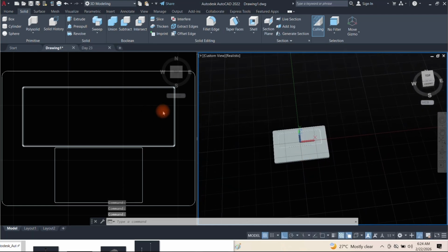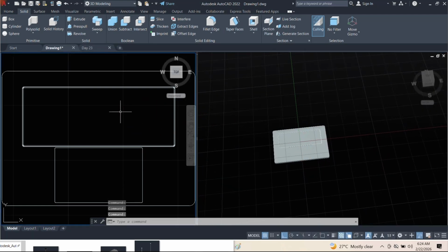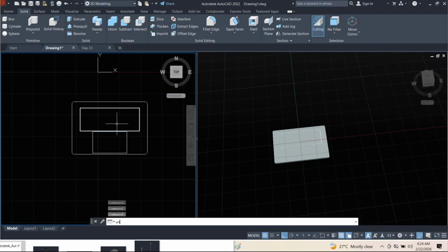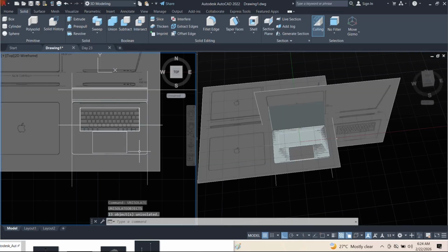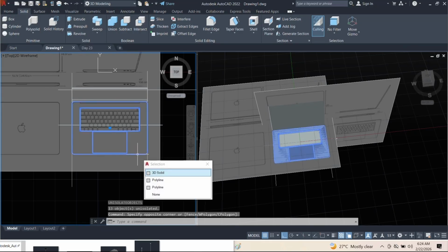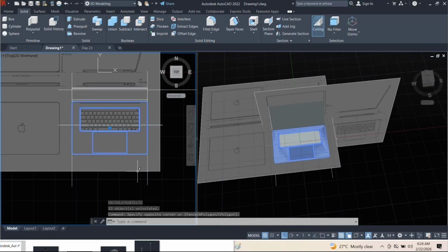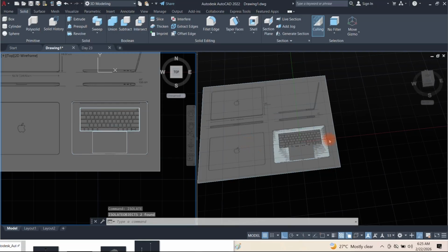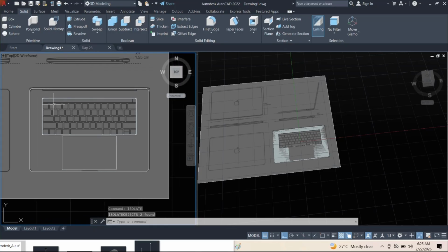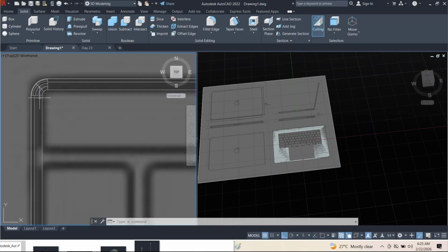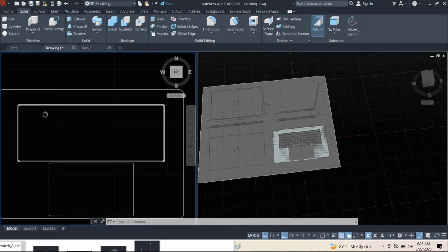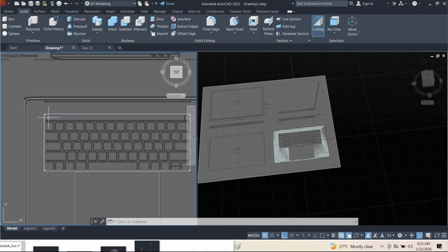Okay, so that's good. So what's next? We'll come here, we'll isolate, and we'll be picking this one by one. So select this 3D solid, and also select this reference image, and then I will isolate both. And why I'm isolating both is because I want to create all of these shapes, and then we can start working from there. So I'll create everything in one go, join them so that we can just extrude everything together.